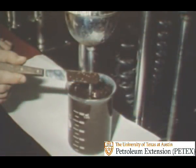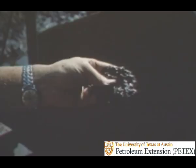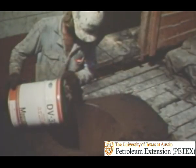And an examination of the mud in the portable lab shows it has a grainy appearance, the bright spots in the mud on the knife. Also, notice how the cuttings stick to each other and are gummy looking. This is an indication of water-wet cuttings. To overcome the problem of water wetting, the derrick man adds an oil wetting agent to the mud.